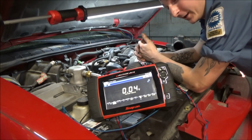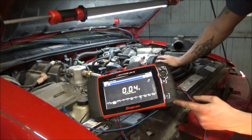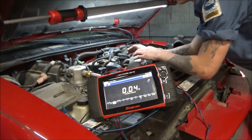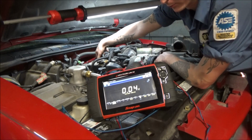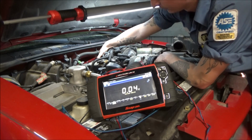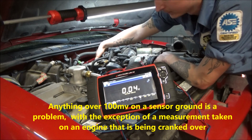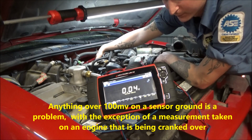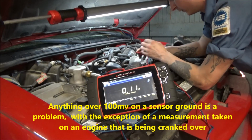But anyways, guys, just continuing on, we're now on the sensor ground, and we're just taking a look at our Vantage. We see 0.04 millivolts, so absolutely nothing wrong with that. I'm just going to go ahead and execute that sweep test very quickly, moving the throttle plate to the open position, making sure that we don't have high voltage on this ground. What we're looking for here, guys, when we're testing the ground, is high voltage. I'm just going to sweep that one more time. This is looking good. No issues there.